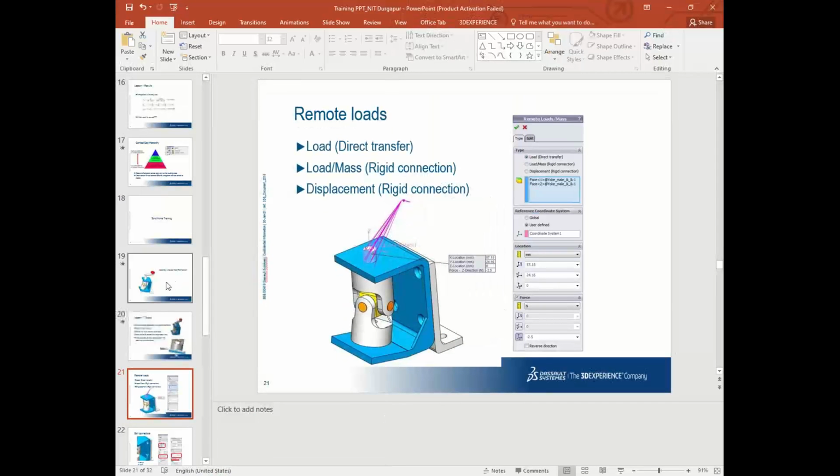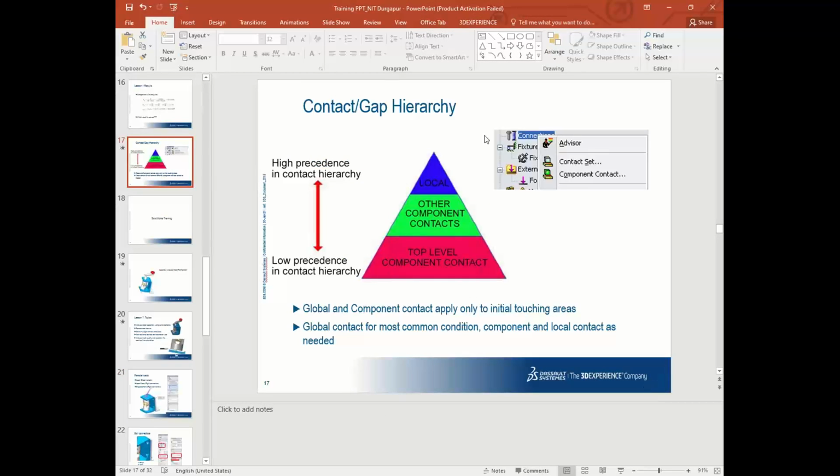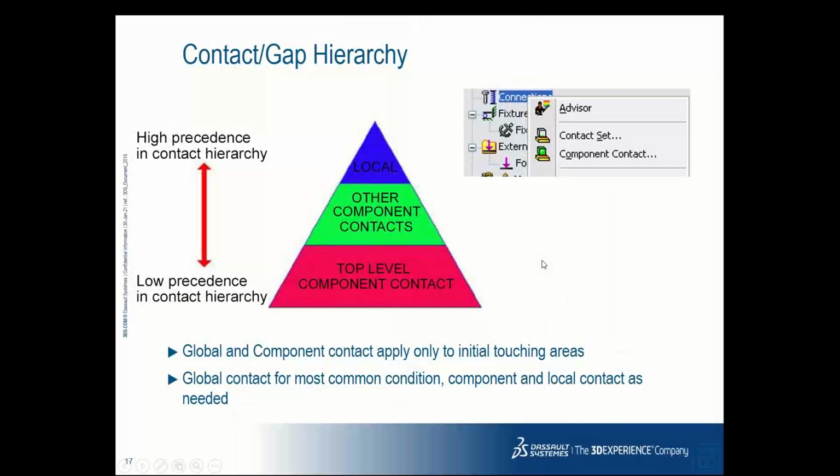Okay, so the next thing is assembly. Since I have imported the assembly in SolidWorks CAD, we apply certain types of mates. You can consider the concept of connectors or contacts analogous to mates. But whatever mates we define in SolidWorks CAD are not imported into SolidWorks Simulation.